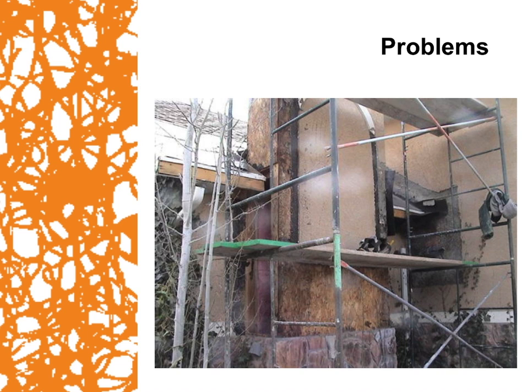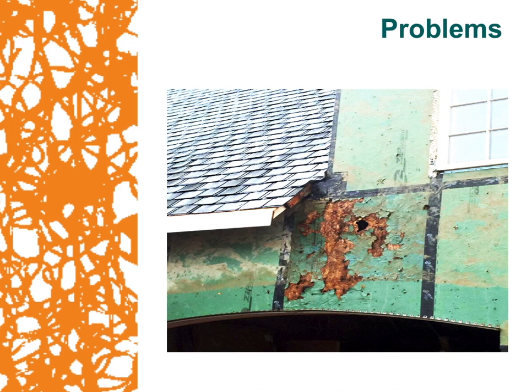The last two pictures that I'm going to go over definitely have moisture problems, but more than likely could have been at least helped or avoided with just a little more attention to detail. The first one is of a project where the moisture that hit the roof and rained down went down the wall and soaked one area, almost like putting a water hose on this one portion of the wall every time it rained. The product that they missed is the kick-out flashing at the roof. With the kick-out flashing, all that rain and moisture would have gone down, hit the kick-out flashing, and been kicked out and away from the structure, giving it a better chance of getting dry and not always being so wet. In the next picture, you'll see the same thing.